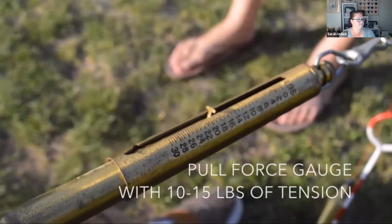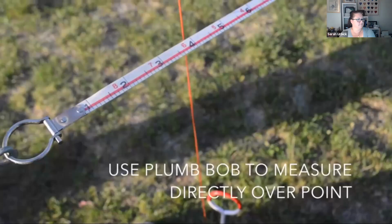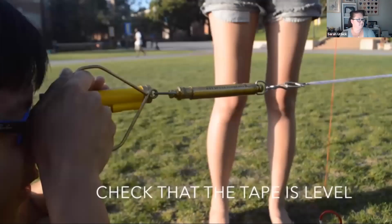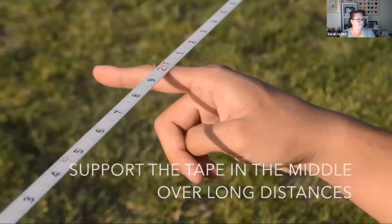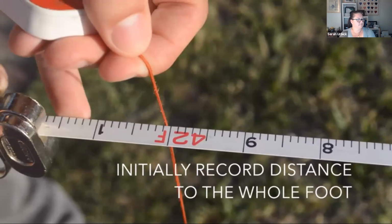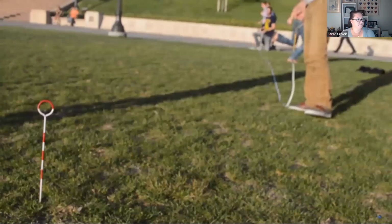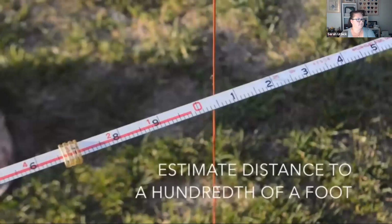At both ends, use the plumb bob to double check that the tape is directly over the point. Then use the hand level to check that the tape is level. Since the steel tape will droop over long distances, have one person in the middle hold the tape. Now, to record the actual measurement, note down the number at the starting point. This will be the measurement to the whole foot. At the end point, the pin should be in the red area. These numbers tell you how many inches and fractions of an inch you need to add to the whole foot.